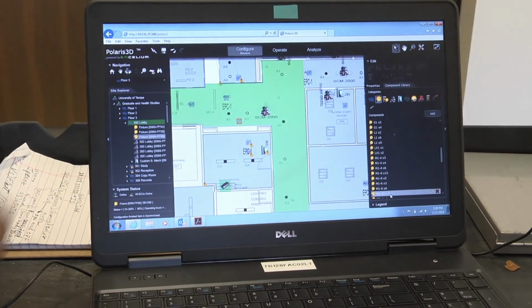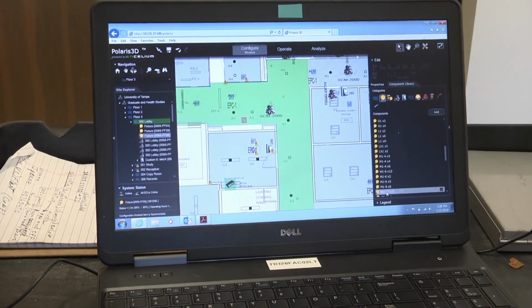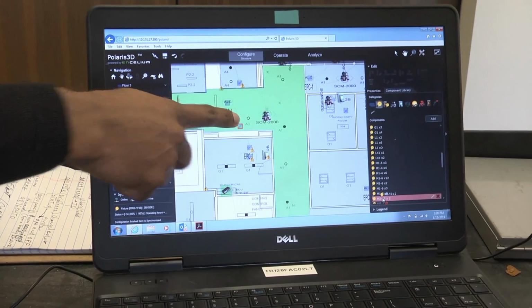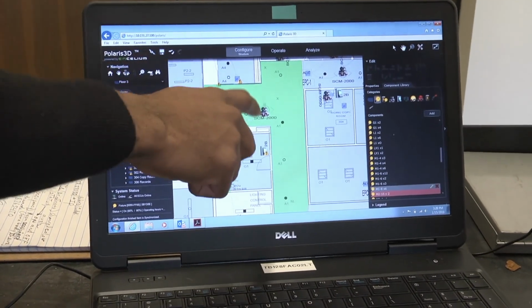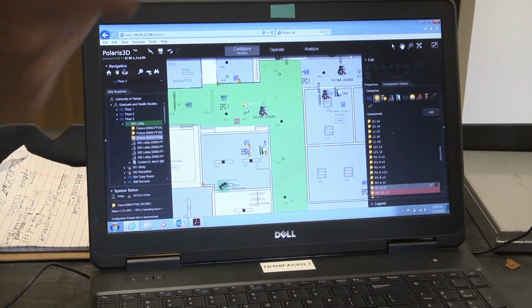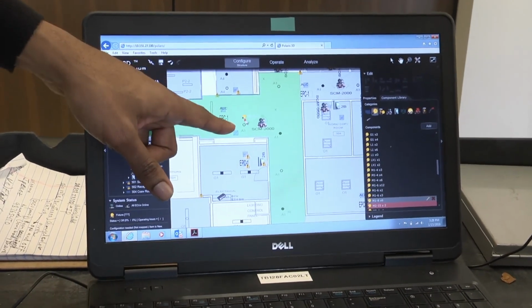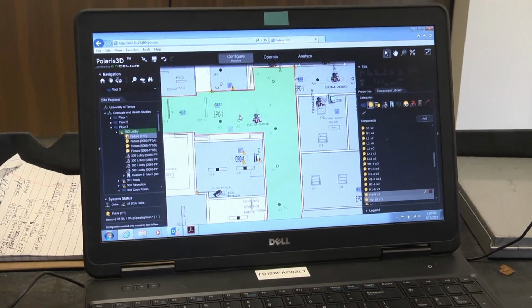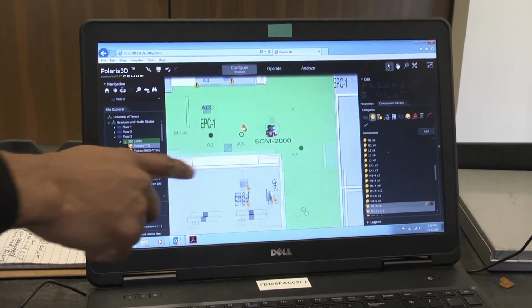So in this case, what you would have done originally, you double click on it the same way, and put it to your floor plan here, and just click anywhere right here. For a second, let me show you. Click anywhere, right? You see how small it is? Now click on the arrow right now to kind of deselect that point. Look how small it is. So you got to zoom into it now, which is why you had it at a 1 by 1.